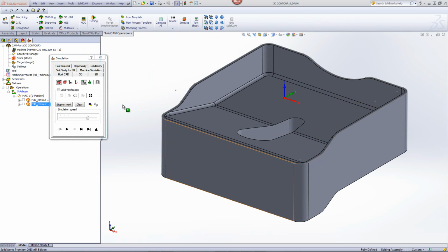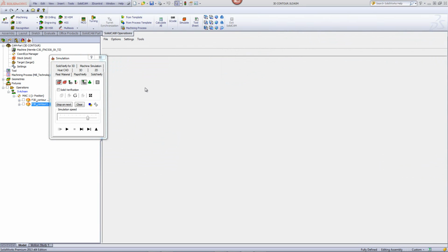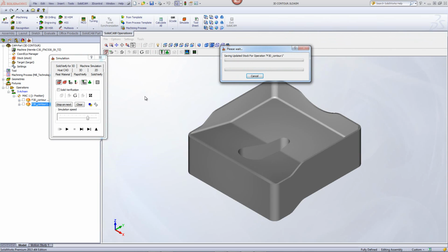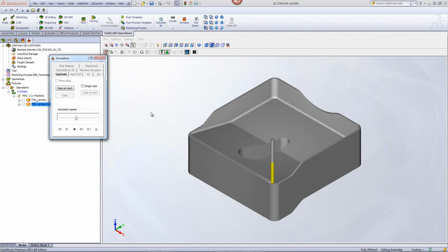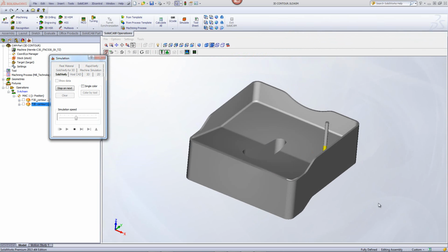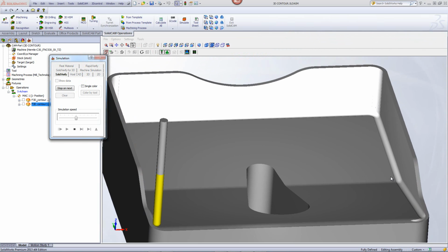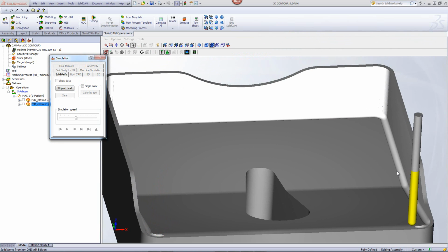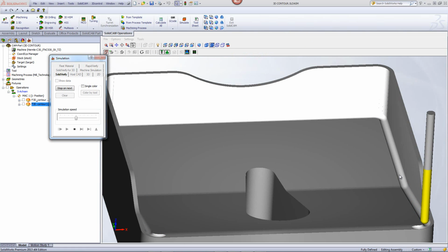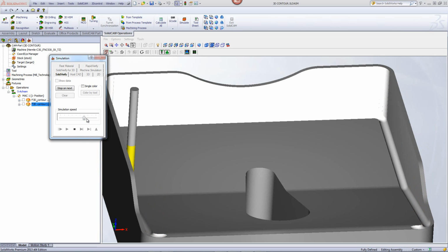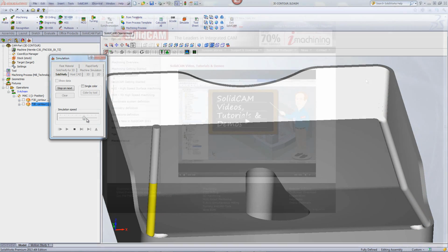Let's take a look at what happens over here, and this time I'll use Solid Verify for the cut itself. You'll see the tool going down into the part, and it's actually starting to gouge into the part itself, forming a groove around that wall over there, going exactly on the center of the chain that I chose. And now it's doing it every 1 millimeter like I had asked it to do. And then at the very end, it'll do its finished cut as shown over here.